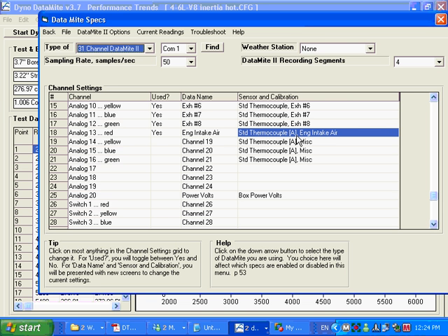Other things that can affect test-to-test repeatability is just engine temperature. If you start one test at 200 degrees and another test at 220 degrees, you are going to get different results. Or that could have been oil temp, it could be water temp, it could be head temp on an air-cooled engine. So you always want to start your test at the same temperatures.